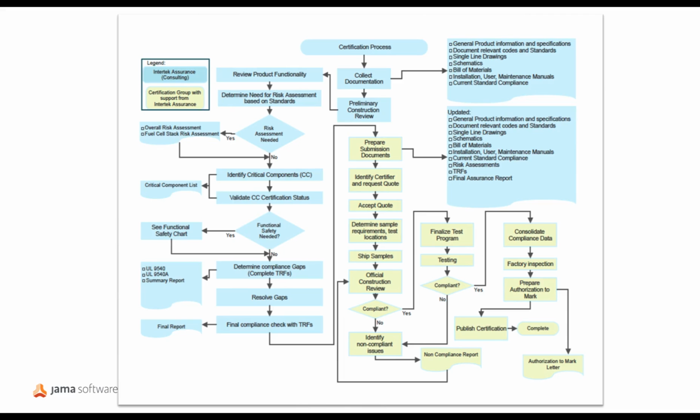When we're talking about energy storage systems, we're looking primarily at UL 9540 and UL 9540A. And the code that drives that is going to be the NFPA 855. And so all these little blue boxes are critical as we prepare for our submission for certification. I will say that not having this information as you enter into certification results in significant time delays, resource costs as far as samples needed, retesting, redesign, etc.